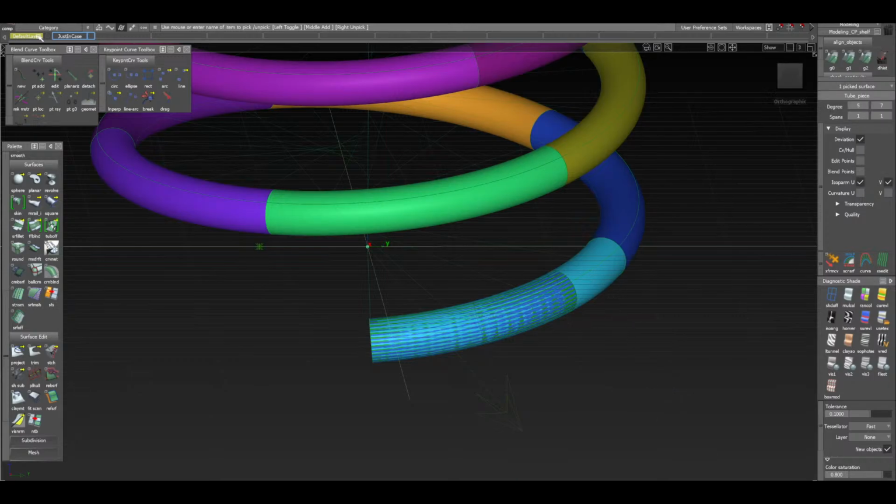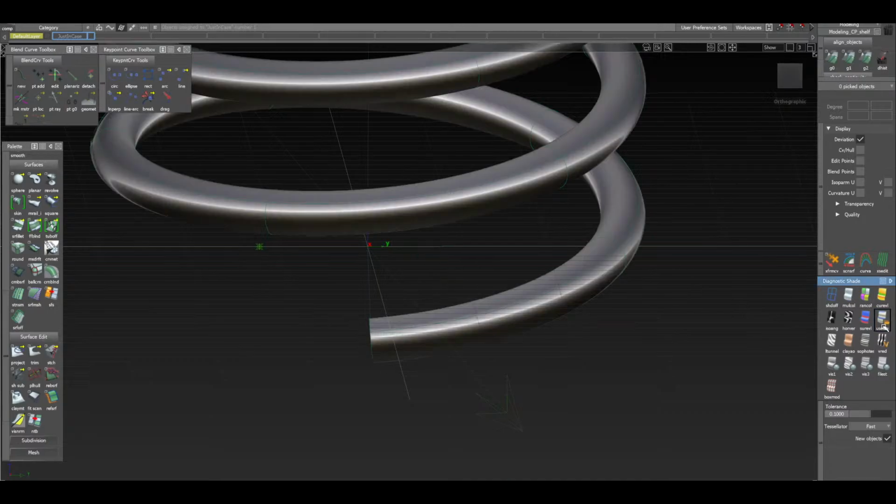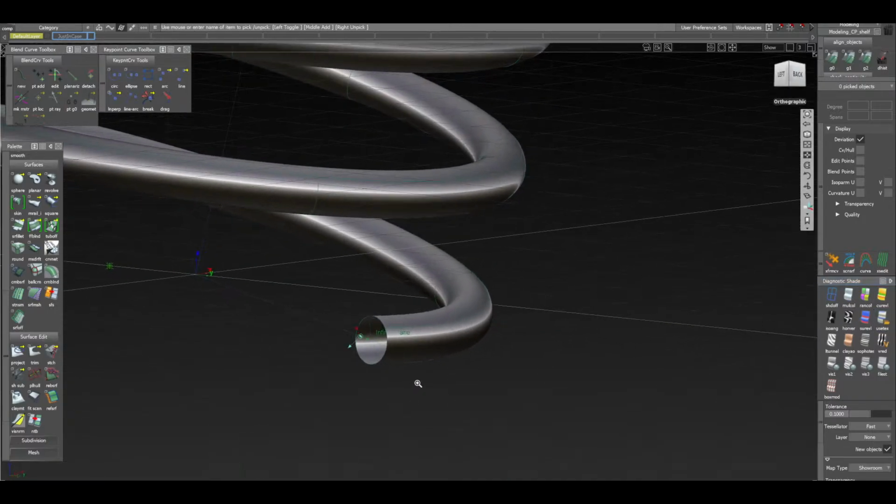Click surface, assign, I'm going to assign it to the default layer, very nice. Turn everything off. Okay, X-ray, I'm going to turn X-ray on, pick the tube, put that on just in case, assign, turn that off. I'm going to pick this other tube over here and assign that to just in case. So all we should have right now is our tubular offset.